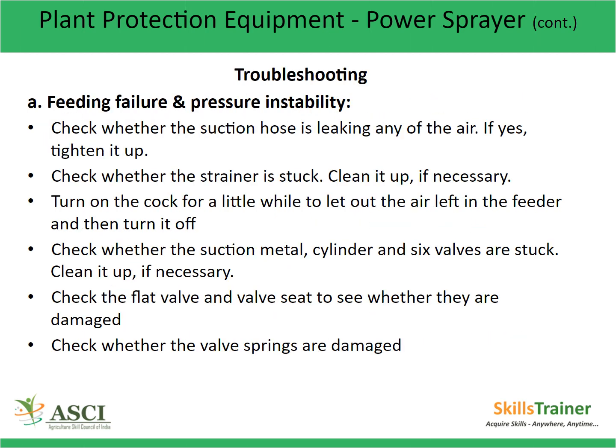Troubleshooting. Feeding failure and pressure instability. Check whether the suction hose is leaking any of the air. If yes, tighten it up. Check whether the strainer is stuck. Clean it up if necessary. Turn on the cock for a little while to let out the air left in the feeder and then turn it off. Check whether the suction metal, cylinder, and valves are stuck.